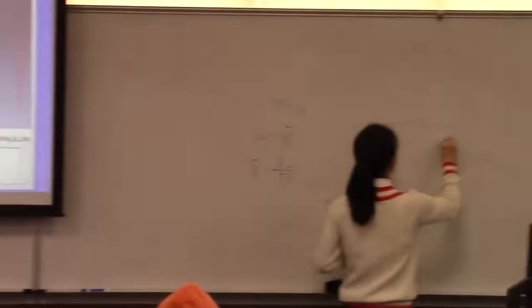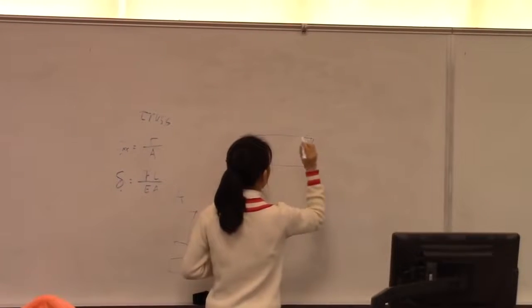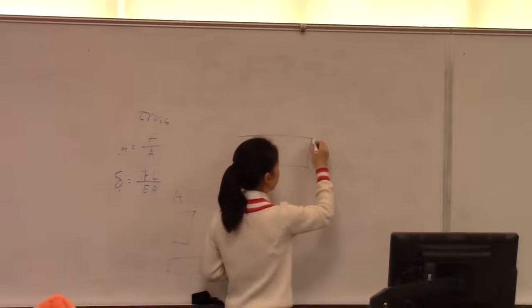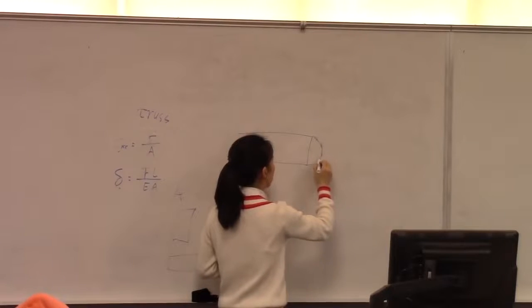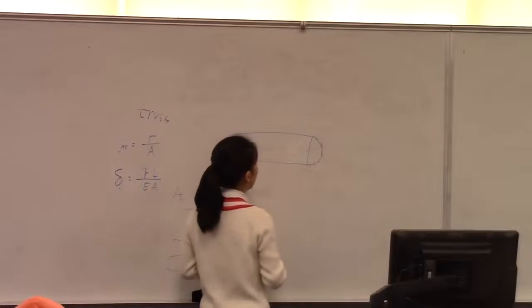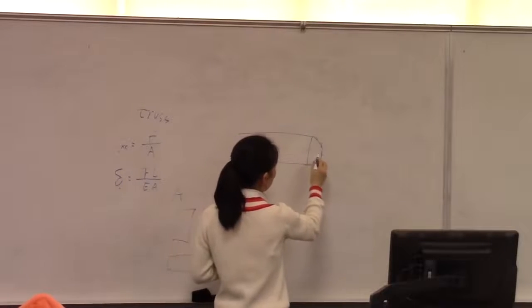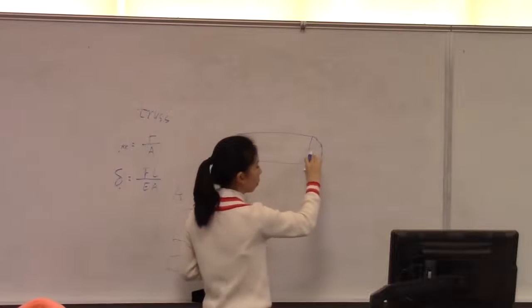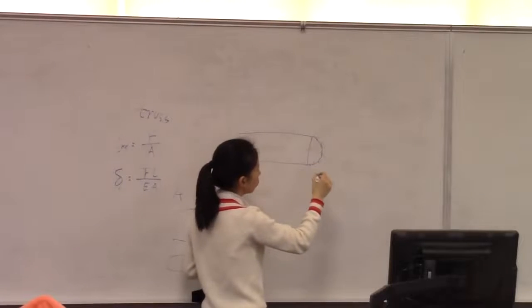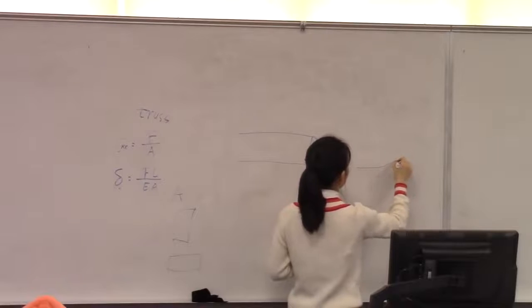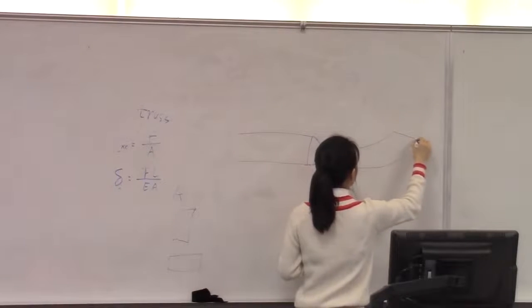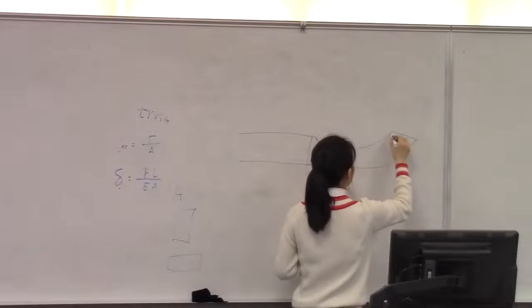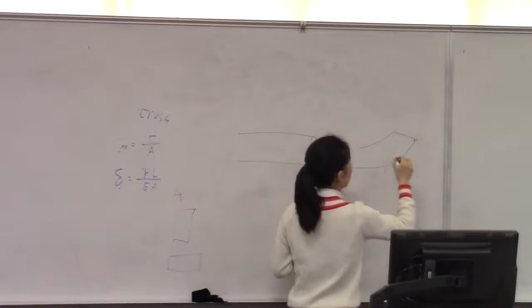Shear flexible means that if your beam is kind of thick, the shear stress is distributed in a way like this, right? This is what you learn from mechanics of materials. And because it's thick, this shear stress cannot be ignored. So when you bend, this shear stress will create a shear strain. What is the definition of shear strain?